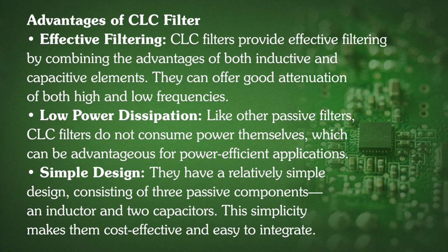Next advantage is simple design. They have a relatively simple design consisting of three passive components, an inductor and two capacitors. So, this simplicity makes them cost effective and easy to integrate. Now, let us discuss the disadvantages of CLC filter.